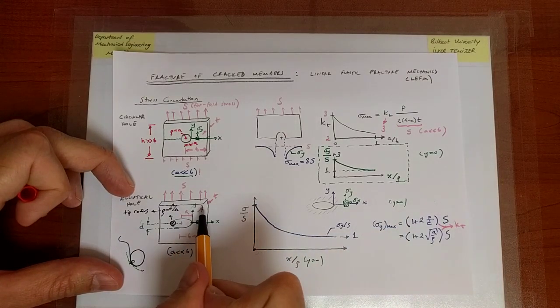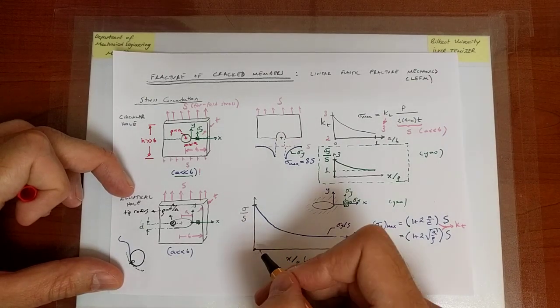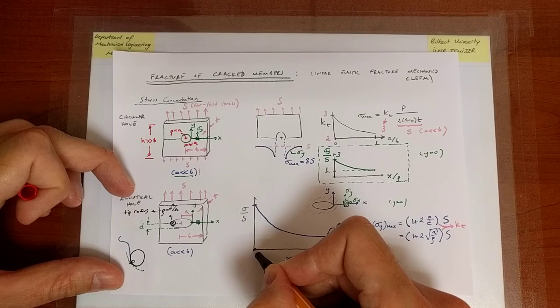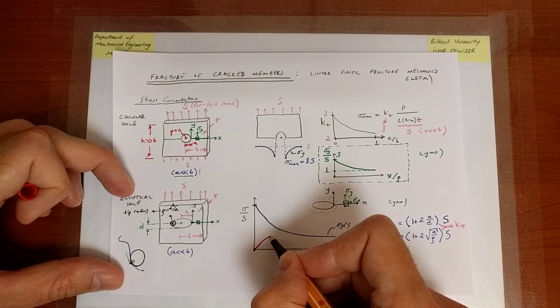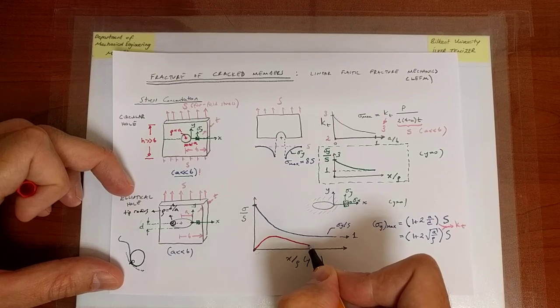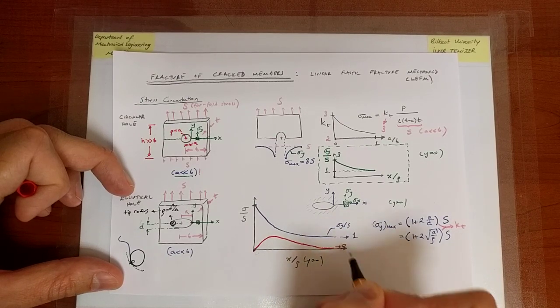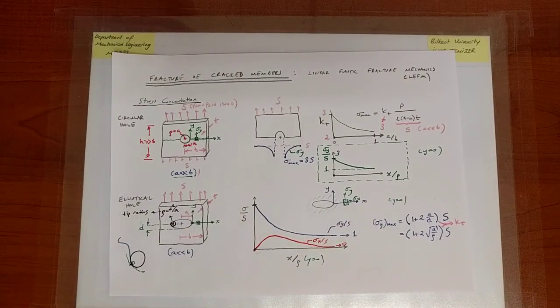But we could do a small free body diagram analysis and ultimately conclude, just from a qualitative discussion, that sigma x cannot be 0 in between. And it turns out that sigma x indeed is not 0. It becomes, interestingly, positive somewhere in between. And then we know it has to decay to 0, so it will decay to 0. So that's the variation of sigma x over s.